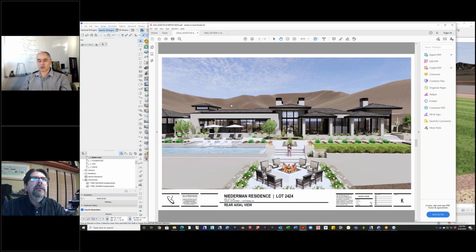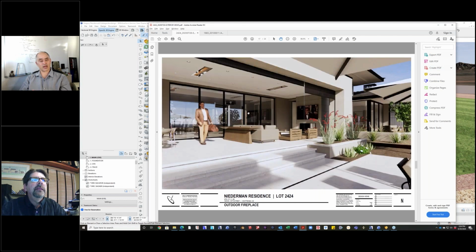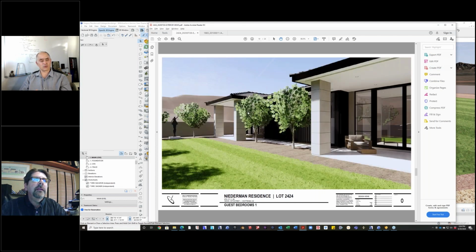Kevin Cabral says, how do we use Google Earth to create a mesh of the landscape? I know we used to have a direct Google Earth connection, but I don't think you have to do it through KML, like exporting to SketchUp format. Well, technically you have to do it through SketchUp Pro, because the regular SketchUp won't do it. But if you go to SketchUp and go geolocate, it'll bring you to Google Earth at the location that you specify. You can section off however big their biggest section is and bring it back into SketchUp, tell it to elevate, and it's not called elevate, but it's something like that that gives it the 3D-ness.